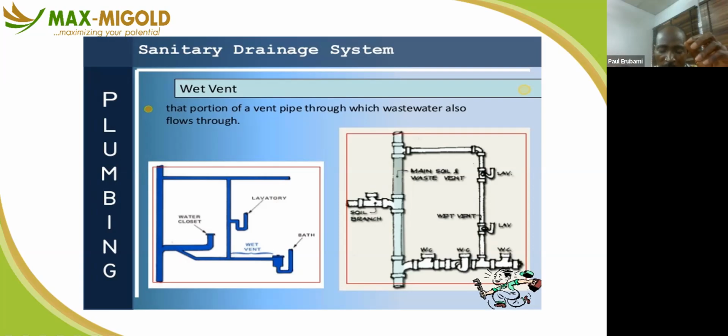From your sewage system. But in some situations where you have a 2-story or 4-story building, you can channel all your roof gutter into that vent. When you channel all your roof gutter into that vent, when it rains, the vent takes out all the water from your roof. And that's the reason why it is referred to as a wet vent. It serves the purpose of taking wastewater away from your roof and also taking odor away from your what? From your sewage system.